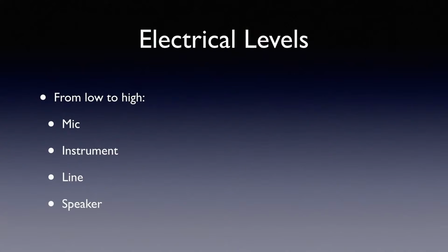And then we get to speaker. Speaker is the only place from amplifiers to speakers where we have to get work done. We actually have to move motors that are the voice coil of the speaker and get sound in the air, pressure moving. So there we need lots of current and lots of voltage to make power, and so there you need big fat wires. When you're talking about going from your guitar amp to your speaker, that's speaker level, so it's going to use large wires.